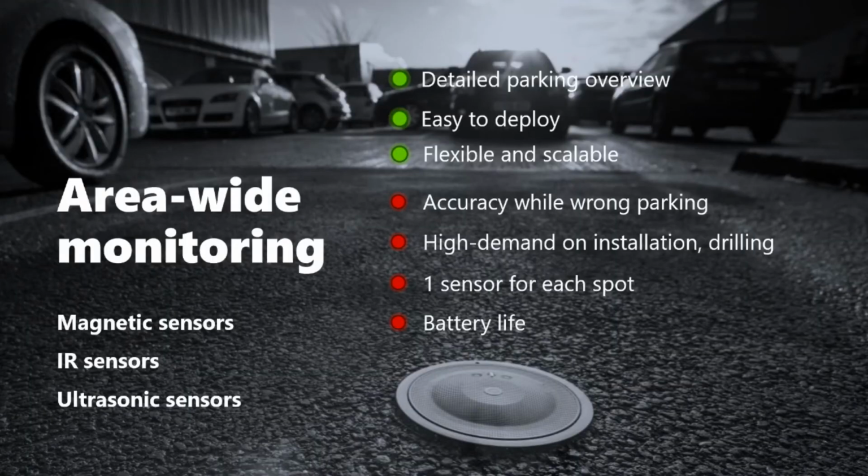Infrared ranging sensors measure the amount of light reflected by an object. These sensors are usually 3 times more expensive than the magnetic ones and also have higher current drain. And the third one here, ultrasonic sensors. Here the emitter dispatches the ultrasound waves instead of light. It's suitable for indoor parking. It's combined with light signals above each parking spot, indicating the current availability.